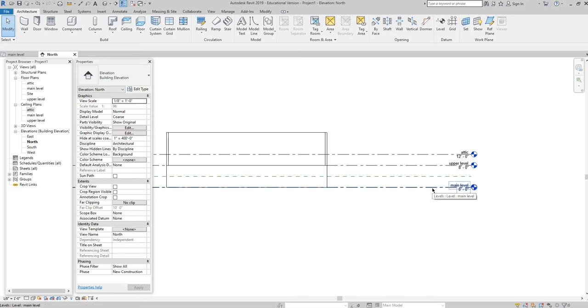So I just showed you how to define a level by using the level command here, LL. I showed you how to create a level that has a floor plate and a ceiling associated with it, all right? There are going to be instances where you need to create levels that don't have floor plans associated with them, right? And that doesn't make probably a whole lot of sense now, but I think the best example I can give for creating a level without a floor plate associated would be to use it to help you create